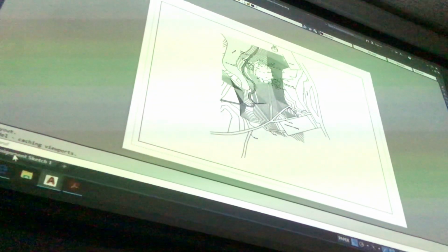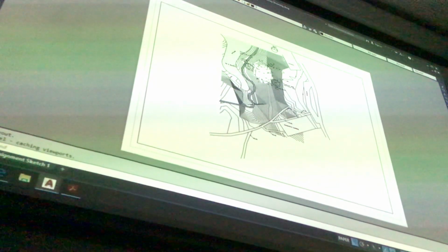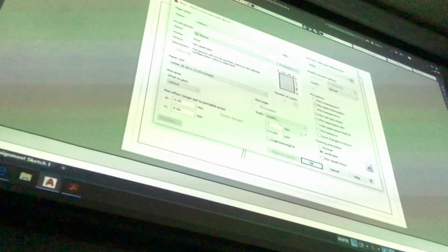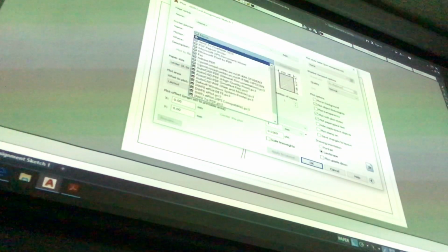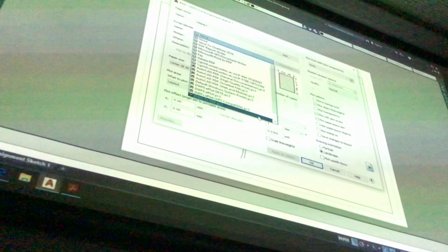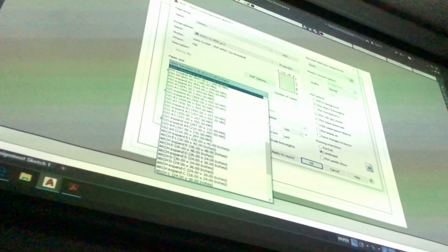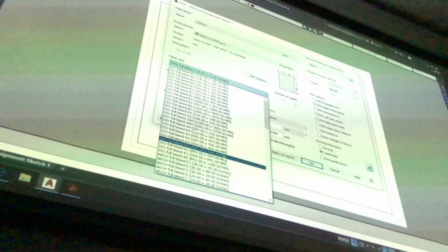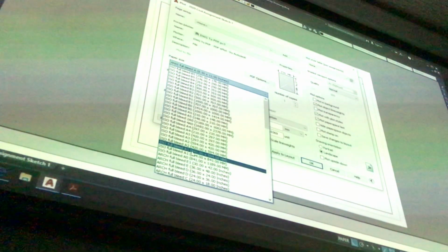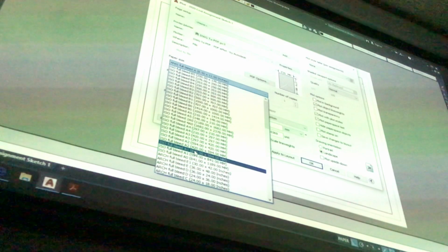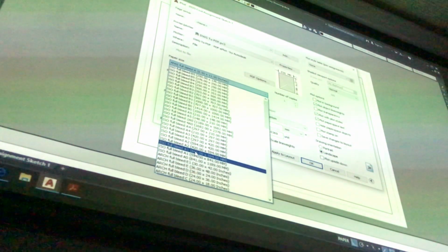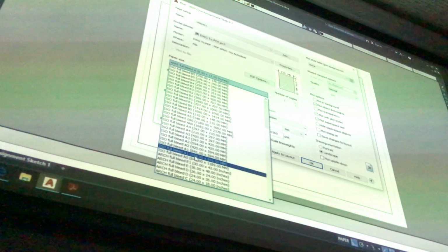So I'm going to go File, no different than last semester. File, plot. So this is all repeat, continue. I'm going to find my drawing to PDF and I'm changing that to your full bleed. So there's nothing different there except that you have to do A1 full bleed. And A1 is 841 by 594. 841 by 594, the big one first, not the little one first.